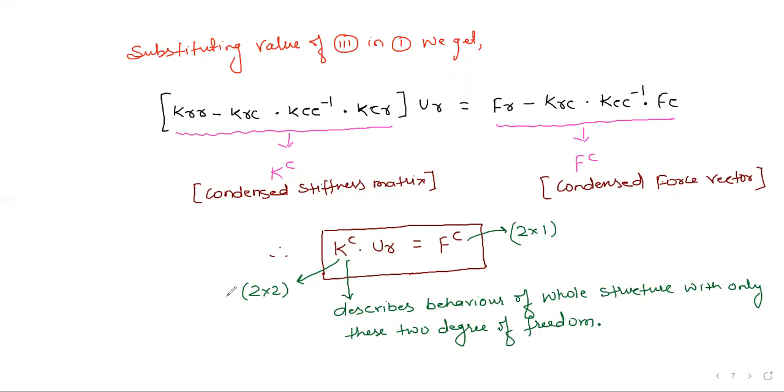Out of that, you want only 3 or 4 degrees of freedom. So what will you do there? You will solve that 20 by 20 matrix. It is going to take a long time to solve that problem, even that lengthy, and it will be a very difficult, very clumsy calculation. So in place of that, we can use this technique to reduce that stiffness matrix to the desired size, how much we want, right?